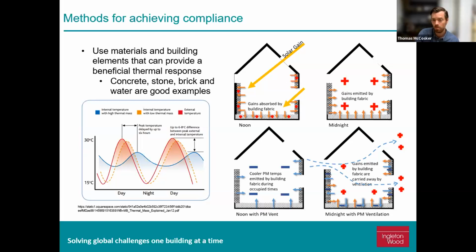The problem with thermal mass is that the absorption can be saturated, as many of us have experienced. A good example of it is last summer in the heat wave. A lot of our houses are older in nature, and at the beginning of the heat wave, they're generally tolerable. The brick or the masonry is absorbing that heat, but at some point it becomes saturated, which is why at the latter part of the heat wave, oftentimes we're all sweating, we're all uncomfortable, and we all wish there was something else we could do.